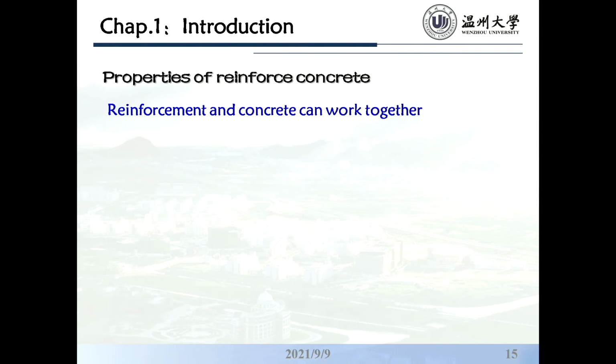There's a desk, a table or something. But in the preliminary design stage, we will use some assumptions, some simplified methods, to transfer these structural members into ideal or theoretical models for us to do the calculation. Like the beam, we will simplify. Like furniture, we will use a uniform load or concentrated load.